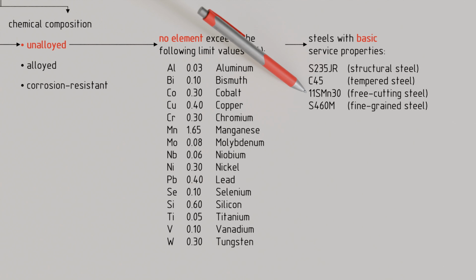Therefore, added sulfur is not considered an alloying element by standard definitions. Moreover, while manganese is mentioned in the steel name, its content is not specified and is kept below the threshold at which the steel would be considered alloyed. The same applies to lead, which is often added to free-cutting steels in quantities below the threshold. Thus, free-cutting steels are generally classified as non-alloyed quality steels according to standards.